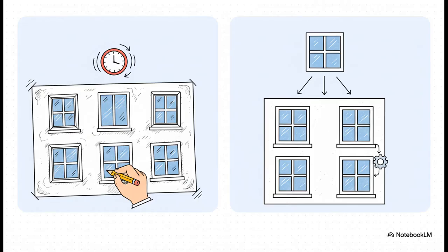And this right here shows you just how massive that leap in efficiency is. The old way, manual drafting, meant you had to draw every single window, every single door. It's so repetitive, it's slow, and you're bound to have little mistakes. With dynamic blocks, you just insert one smart object and tweak it. It guarantees everything is uniform and lets you make instant updates across the whole project. The time you save is just enormous.